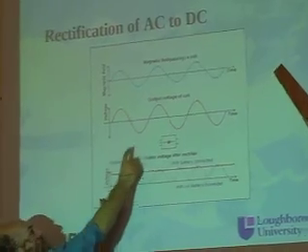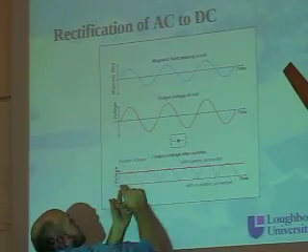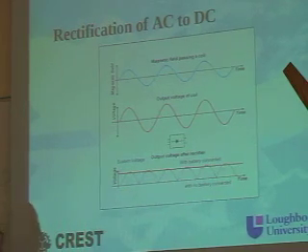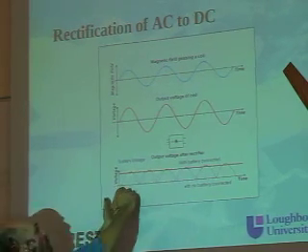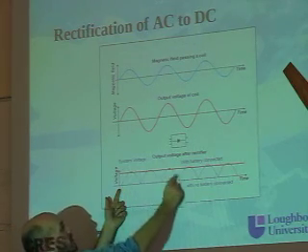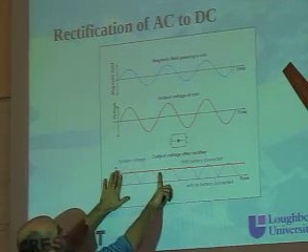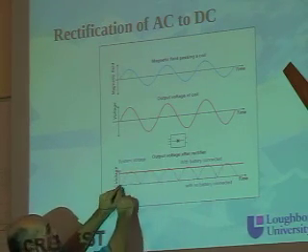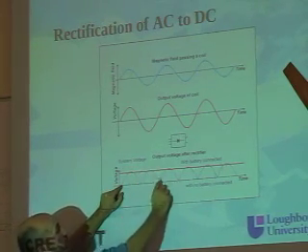DC, what it is, this lump here actually goes positive, so you get these lumps of voltage. So if you were just watching it on the output of the rectifier, you will see a voltage going up and down at a frequency. This frequency is the frequency at which the thing is being rotated, depending on how many poles it's got. So you get this voltage here.